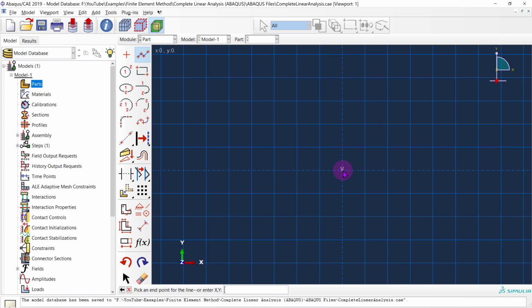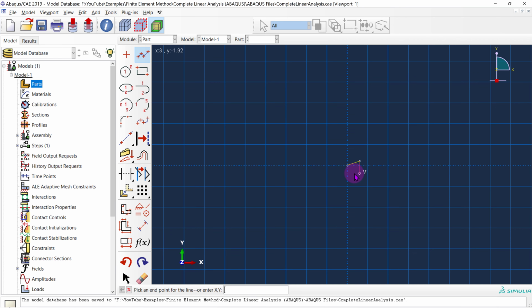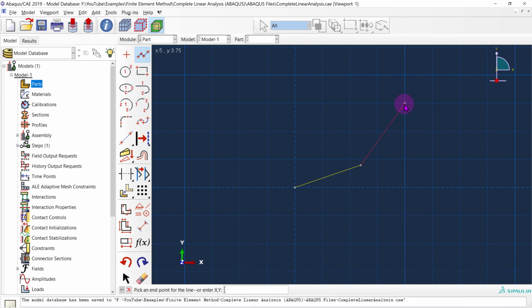And if I go enter, it already selects that point. And then it allows me to specify the next point. So our next nodal point we said was 3, 1. So 3, 1, enter. I have this point over here. We can zoom in a bit. And then our next point was 3.5, 3.2, enter. And then our last nodal point was 0.5, 3, enter.